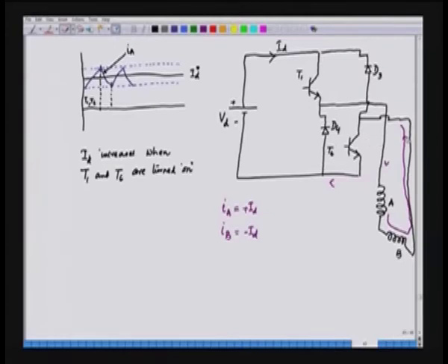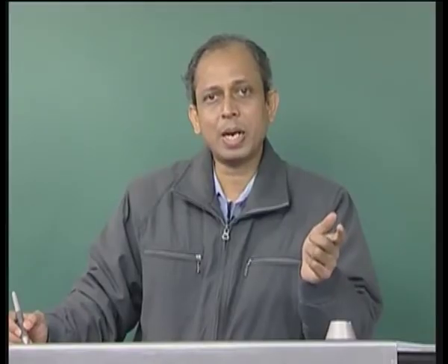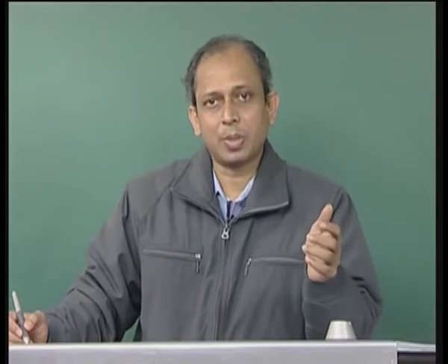So, the transistors are now off. So, the current has to be maintained. So, the current which was flowing in this direction, positive here and negative here, will look for an alternative path, and the alternative path is provided by the diodes. The diodes are, in this case, D4. So, the current will come from D4, D4 turns on, and then this current will flow back through D3. So, in fact, when we turn off T1 and T6, automatically D3 and D4 will be turned on because of the nature of the current.